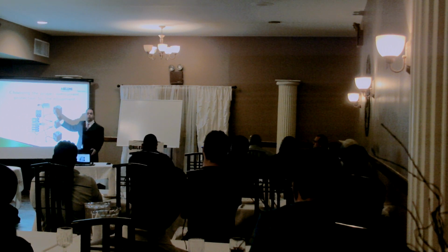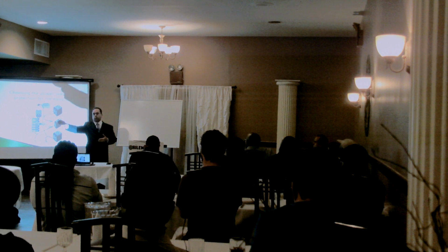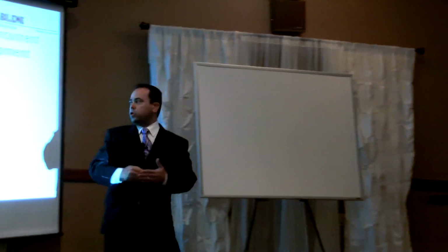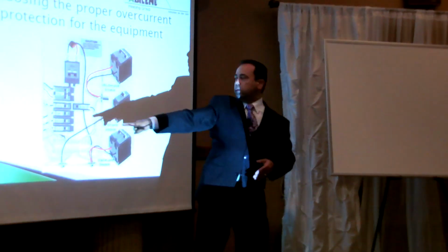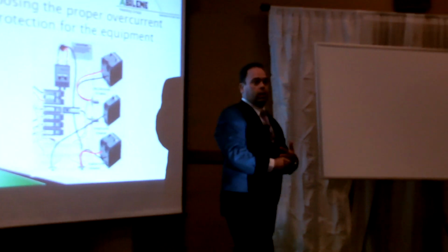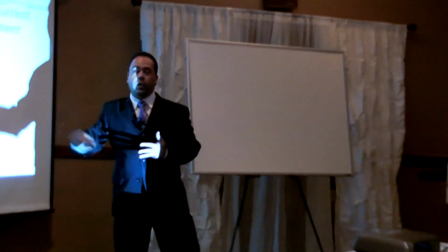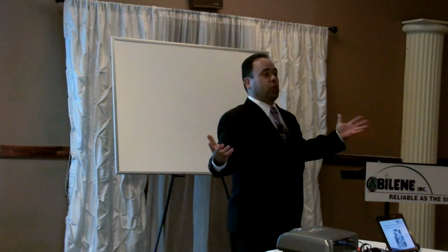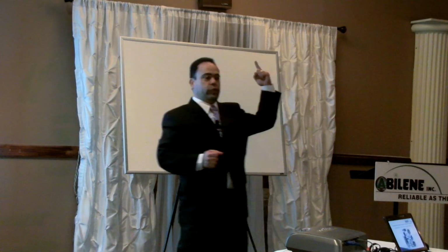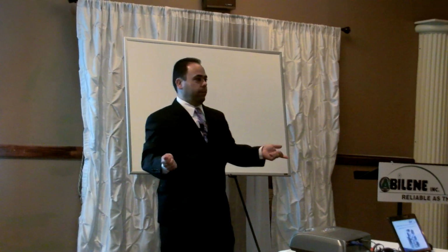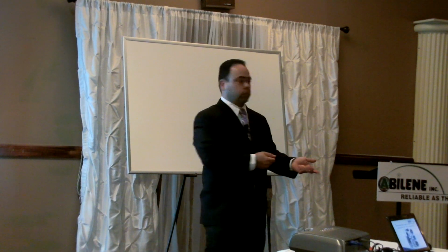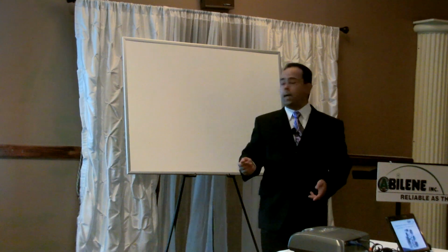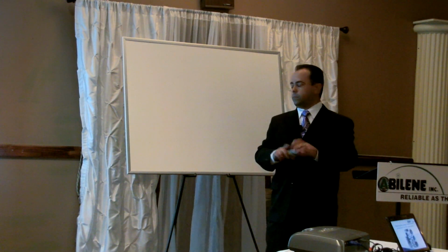And they're sized for what they're providing power to, or what they're protecting is a better word for it. So if I have a range or a cooktop, obviously the wire is going to be a little bit thicker, and the amperage on that breaker is going to be larger, because a cooktop is a heating element, and it draws a lot more electric than a light fixture or a lamp. Or a small motor. The larger the motor, the larger the wiring too. Everyone get that? Okay.